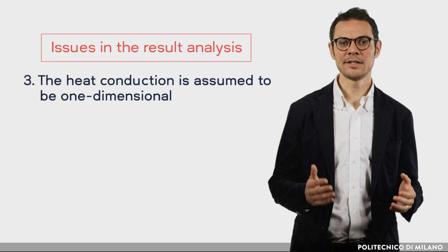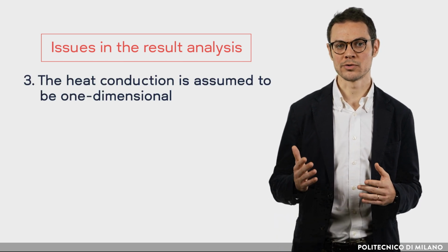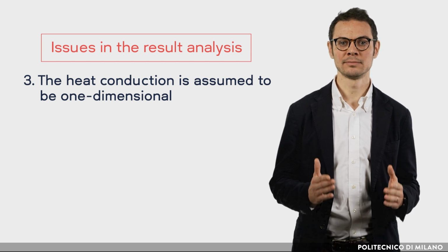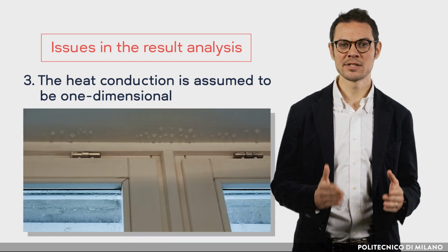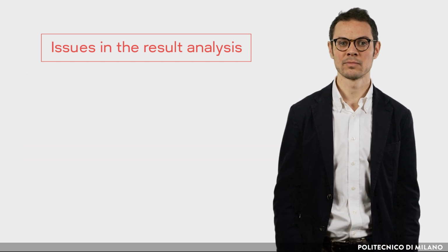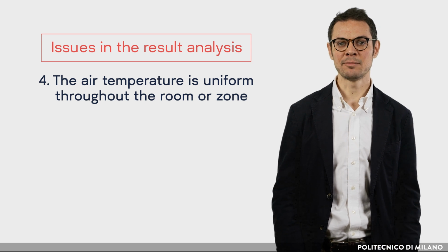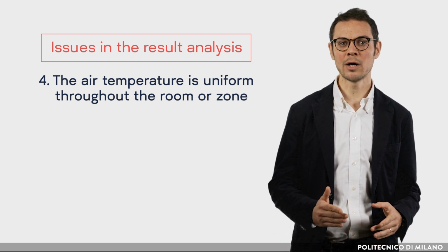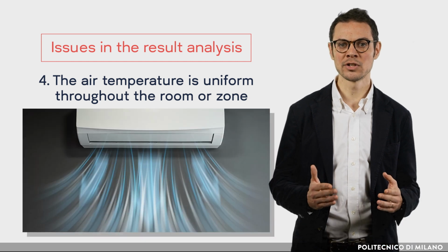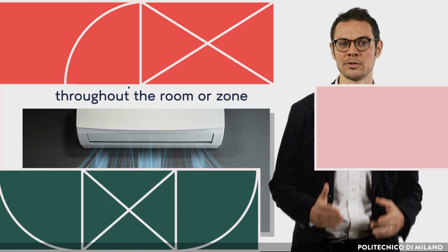Third, the heat conduction through the room or zone's elements is assumed to be one-dimensional. Thus, thermal bridges cannot be considered in the overall simulation. Fourth, the air temperature is uniform throughout the room or zone. Thus, the air stratification is not taken into account.